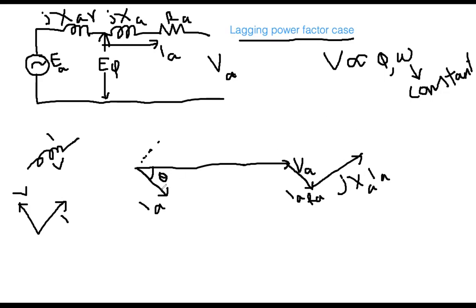So I was explaining how to plot jXA. On this line, your jXA into I versus this one, your I. This means jXAI will be 90 degrees leading. So actually from here you should go 90 degrees in that way. But because I want to go from the voltage endpoint, I am drawing a parallel line to this one, which is jIXA.